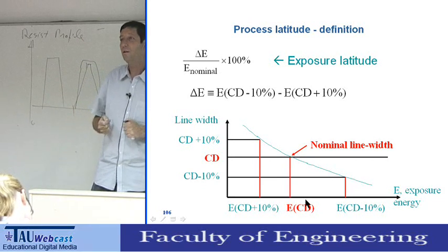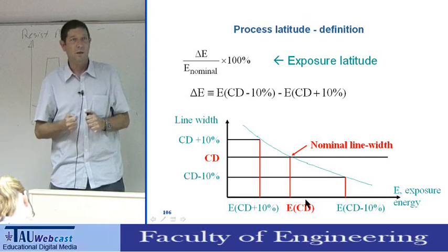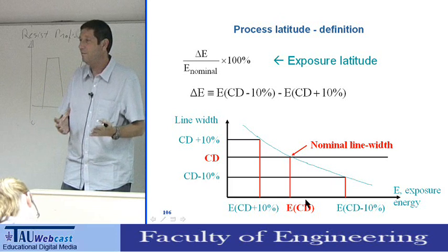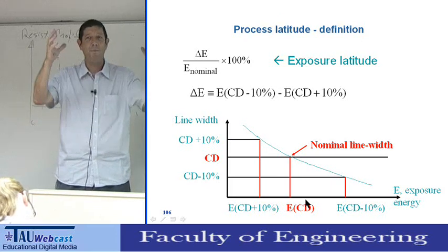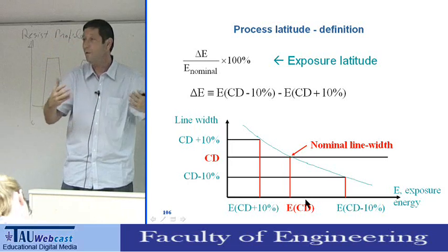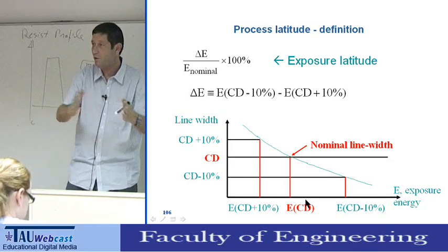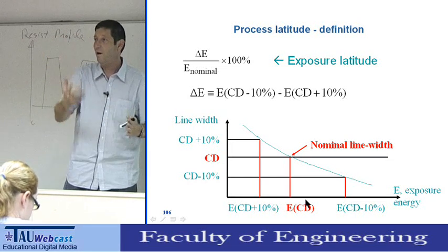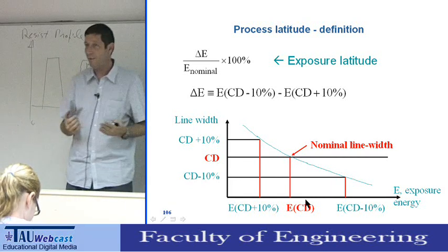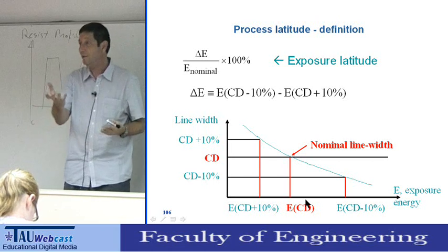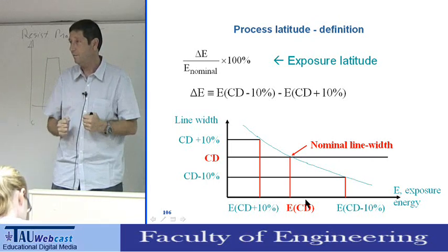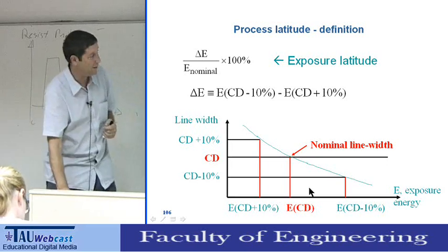And one trick that people can do is, while exposing, you measure the light intensity. Let's assume that you're using a lamp and your lamp is getting older, the light intensity is going down, so you can compensate. You can change the duration of the exposure as a function of your lamp intensity. And in many systems, in the past, people actually did it. They put in a light meter and you design the dose, not the intensity. And the system automatically adjusts the dose.